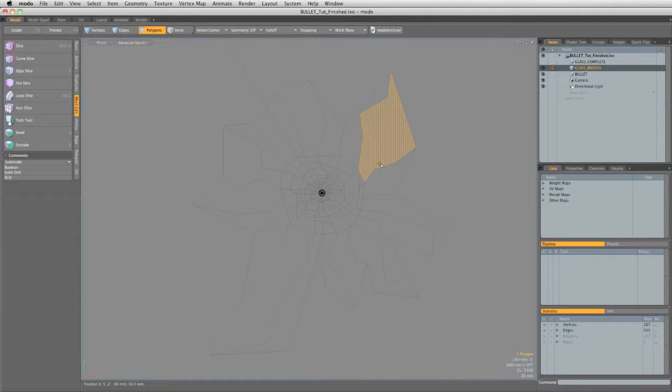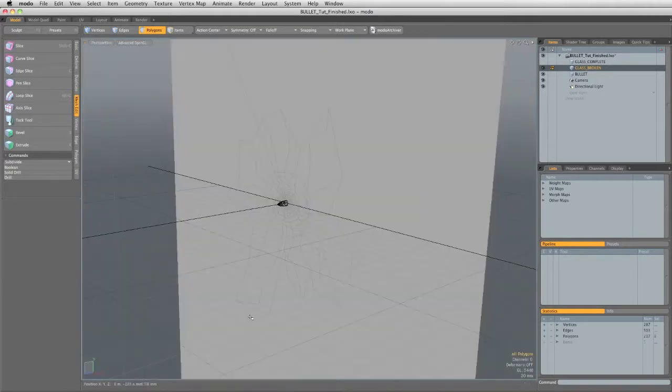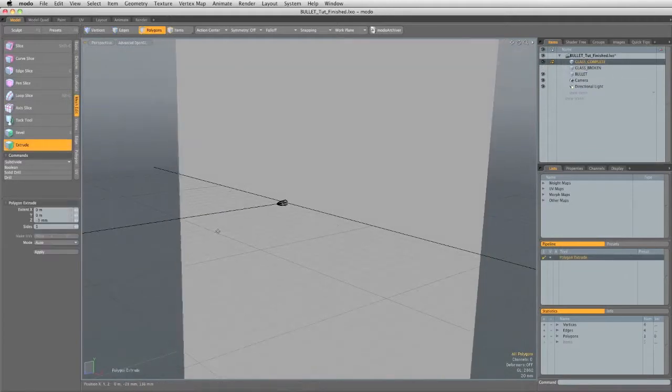Now these aren't going to be individual pieces of glass. Having it like this just allows us to define the geometry for the fracture line, but it will become more obvious why we've done that in a minute. So now we can extrude the glass to make it three-dimensional. That's pretty straightforward with the glass complete layer. We can just run extrude, and we'll just extrude it by -3mm on the Z.